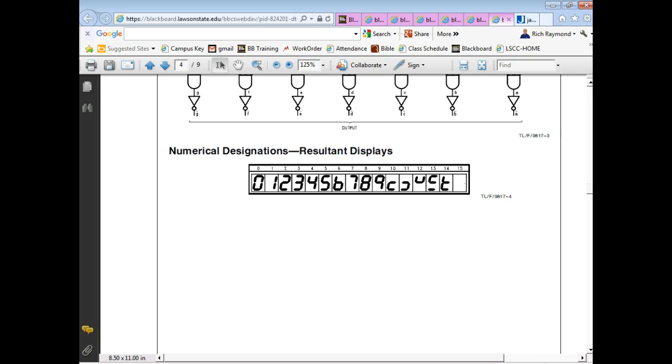And we used to teach how to make them, by the way. We used to make them here. I tell them how to make them. To save money, we didn't use a 9368, which is a hex decoder. We used 7447s. And of course, the codes they sent out were binary codes, but people don't understand the binary codes, so we'd display them in hex. And we use these guys, and all you had to do was figure out what an A was, a B was, and a C code.